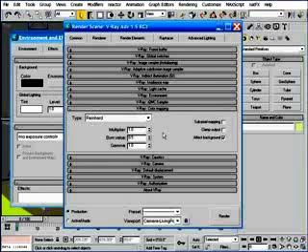So this is better than just using the default linear option, which is almost always going to give me some burned out areas. So either exponential or Reinhardt with a burn value of 0.5 is a good place to start. I also want to enable these two options here, subpixel mapping and clamp output. These are two options I always enable by default, and I consider a necessity, and they have a negligible impact on render time, but they certainly have a tremendous impact on the quality of your rendering.